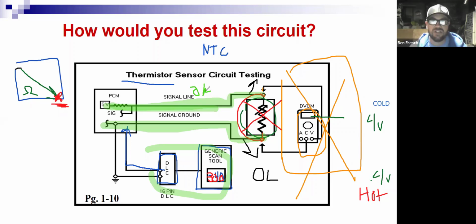It's good. So if I have a coolant temperature sensor that's not functioning right, and I've done this check, I'm going to have only a couple things left. It's either I have a defective sensor, or maybe I actually have something wrong with the engine. Like let's say it has a coolant leak and there's no coolant to touch the sensor, right? If you had no coolant in the engine, then the sensor's not submersed in coolant, and it's not going to work correctly, right?